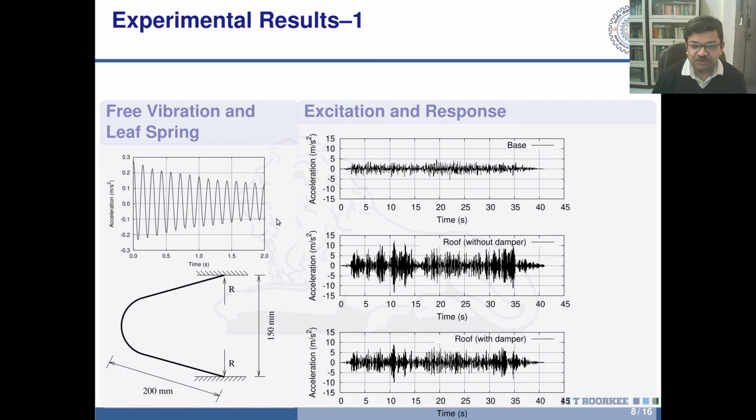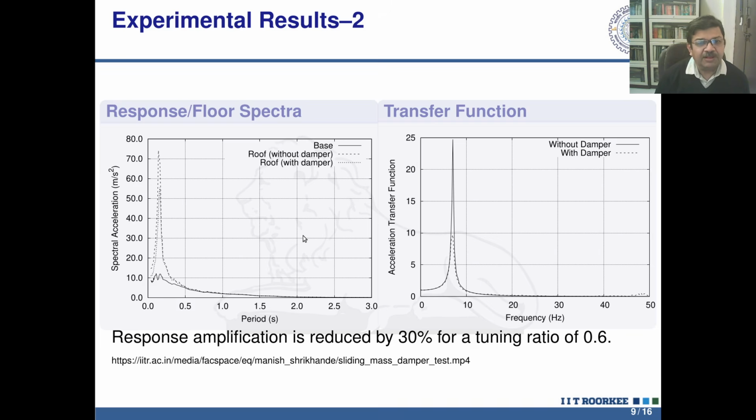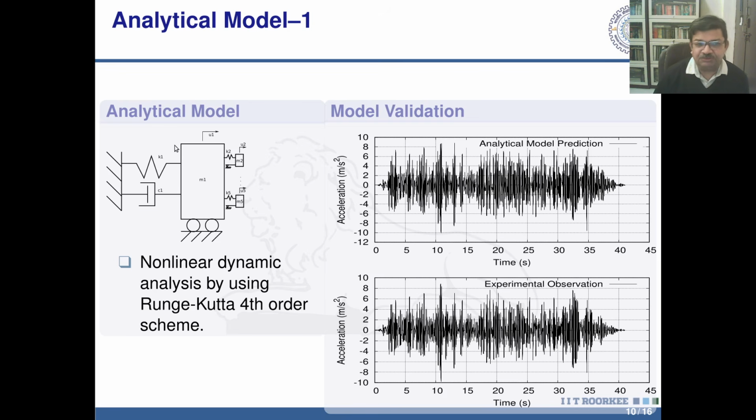The damping is about 0.9%, and natural frequency is of course 7 hertz. The mass we calculated according to the dimensions of the roof slab, and on top of it we have these four auxiliary masses supported by the spring and this friction interface.